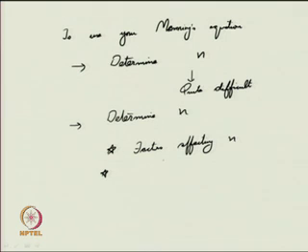Then you can also use various available tables in various engineering offices, various academic institutes, various places related to open channel flow. You will find printed tables for the roughness coefficients of various surfaces. You can use them, there is no need for you to individually compute the value of n.